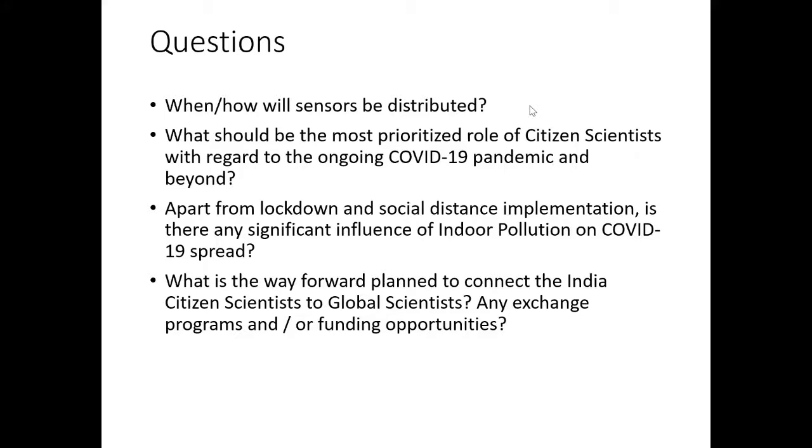Also, if something was to happen to one of the sensors, we would still have the A or the B channel operating correctly. That allows us to identify whether something has been lodged in the sensor or if there is a spider that crawled in. We can then determine whether or not we need to perform maintenance on that device.